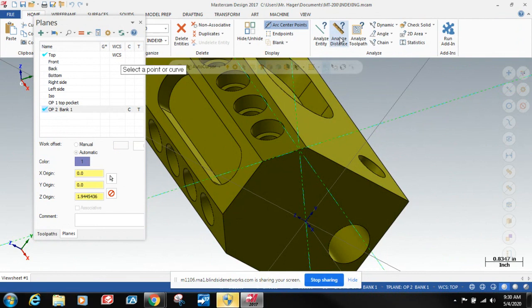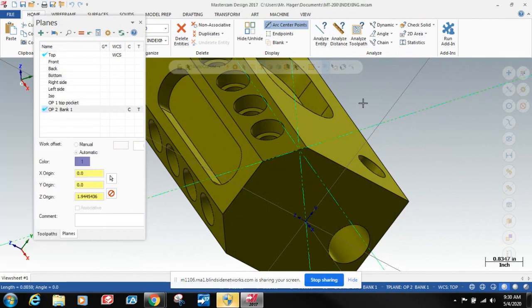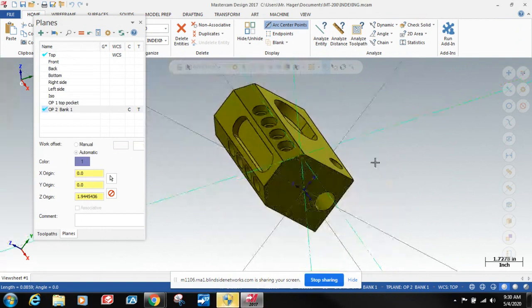I'm running Mastercam 2019. So for me, I had to choose the reselect button and then move it to the point of origin that we need. You might have a different button, like you're rocking 2017. So reselect and then select the origin point. Bingo. Press the reselect button and it'll let you move your gnomon.